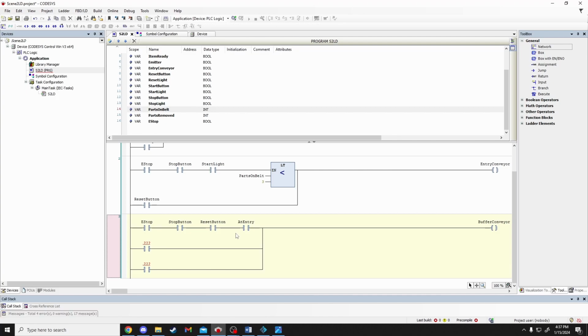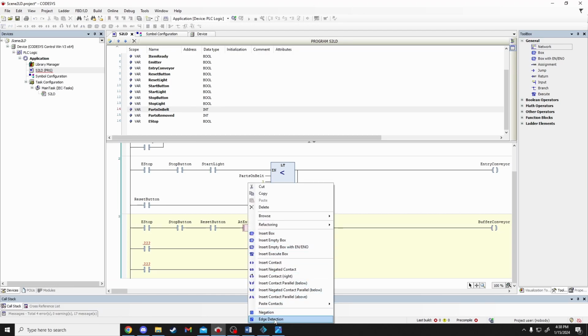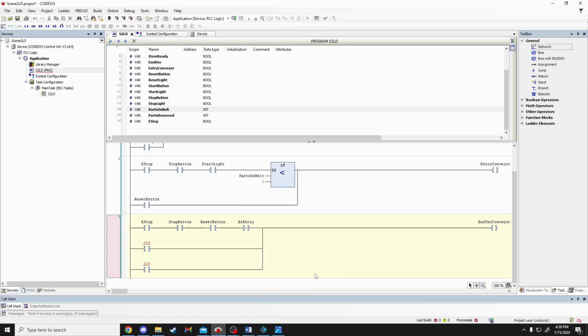Because these are retroreflective sensors, they are by default on. The light is emitted from the emitter, it bounces off the reflector plate, and then it's read again by the sensor. So it's got a default on signal. We want the signal to go off. So when a box gets in the way and interrupts the signal, then that will be the desired condition. So when the sensor is off, we want it to give us power to the conveyor. So that's why we have that there.